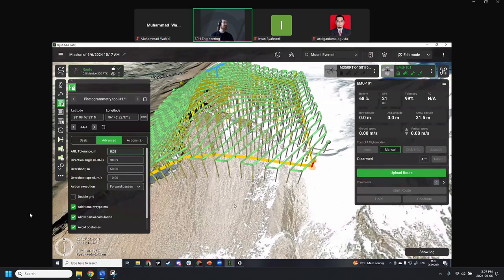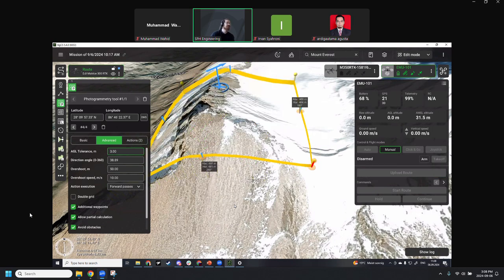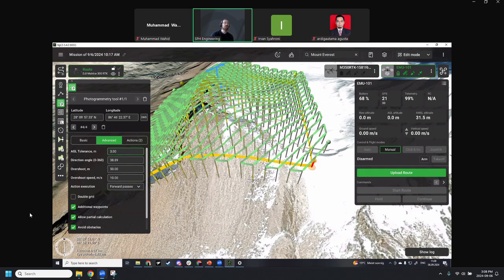Of course, you want to make it as low as possible, but if you have too many waypoints, the stutter will decrease the quality of your data. So in this case, just adding one of, for example, 3 meters is already going to provide a more stable flight, which will provide more quality data. Depending on the product you want to get, you'll have to choose personally.